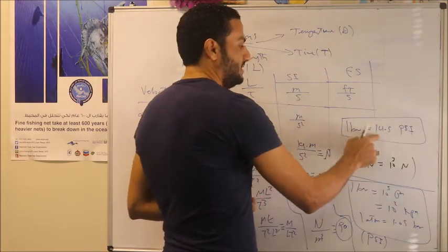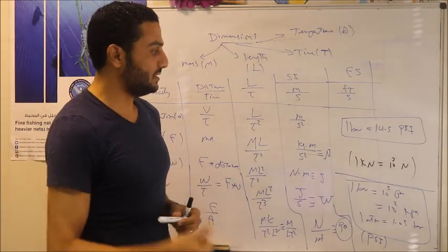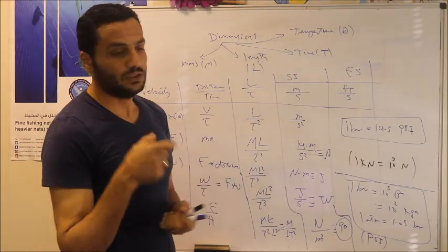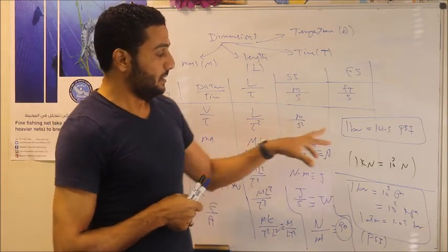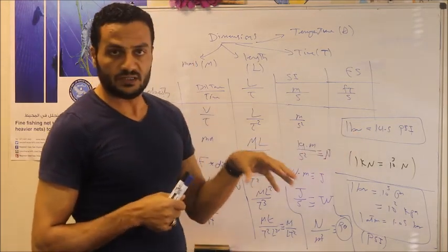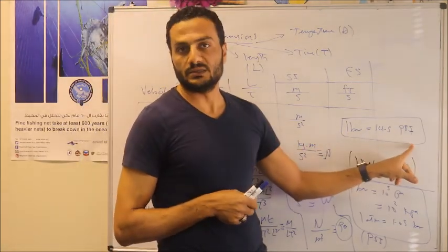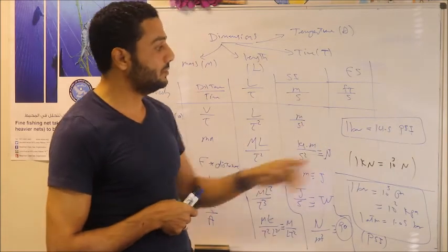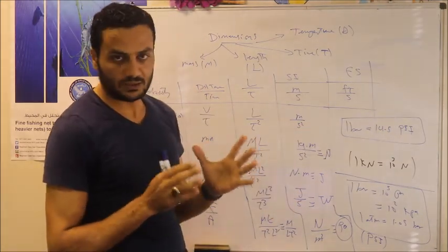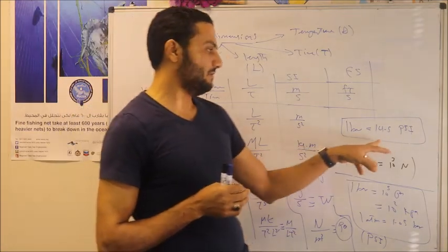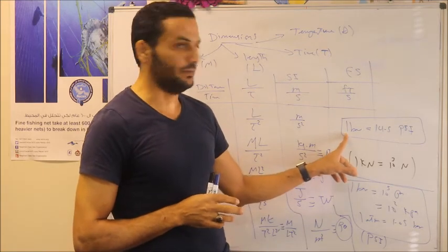If you went to the puncture shop to fill the car tire, to increase the car tire pressure, you will find the measuring device has 2 scales. One scale is in bar and one scale is in PSI. Usually you have to set this value to about 35 PSI, which is the car tire pressure. 35 PSI is almost equal to around 2 to 2.5 bar.